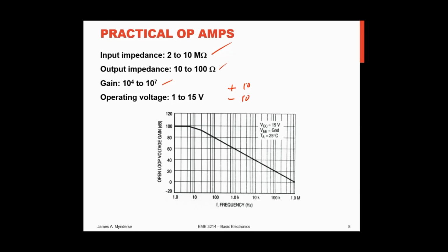So that's a little bit of an inconvenience, but in practical operations, if you just had a couple of 9-volt batteries, use my artwork, and this is plus, and this is minus, and this is plus, and this is minus, and I connect these together, connect this to my system ground, this becomes V plus, and this becomes V minus to power my op-amp.